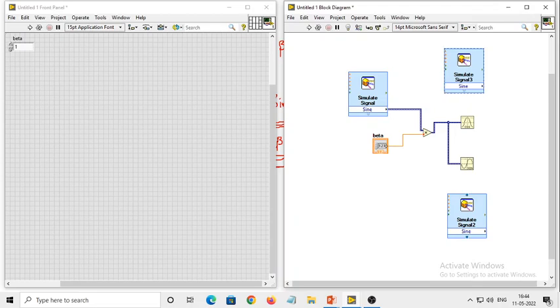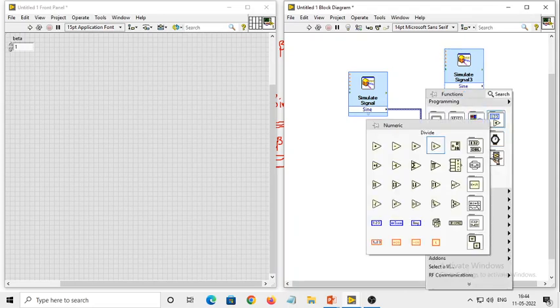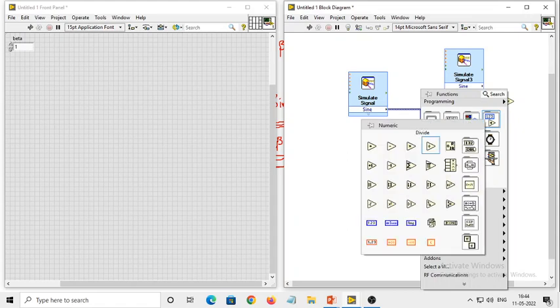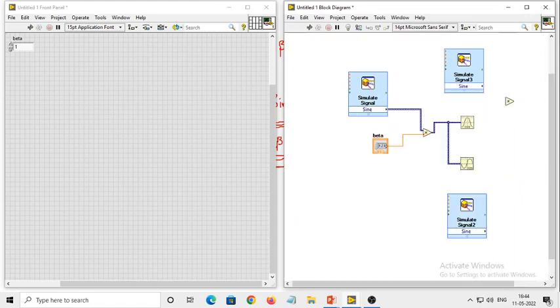Now what you need to do, you need to multiply the outputs of this and also this. So you just right click, put a multiplier, again one more multiplier on the bottom of your screen. Then you just need to give inputs. One input is coming from cos 2 pi fct and the other one is cos of beta sine 2 pi fmt.